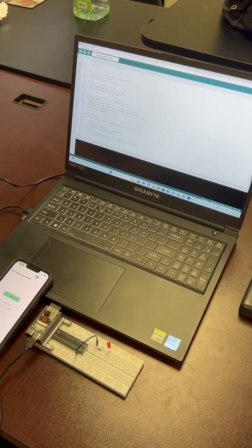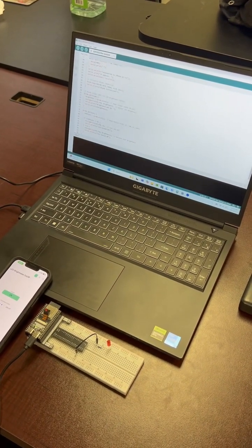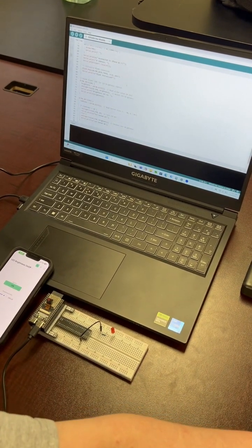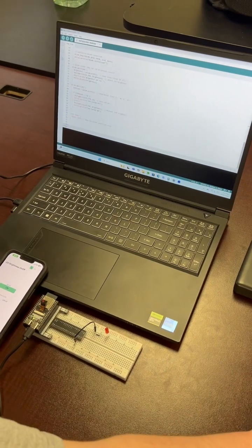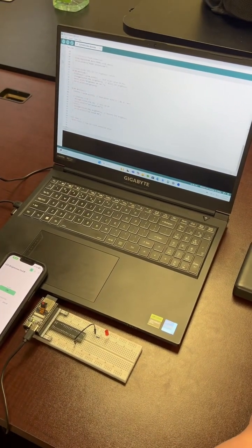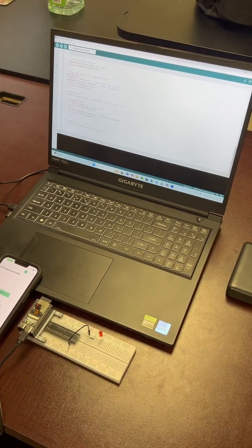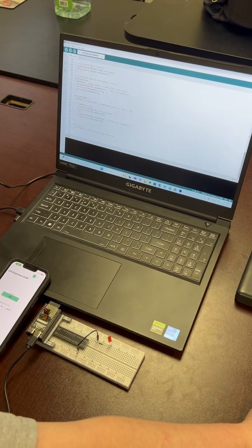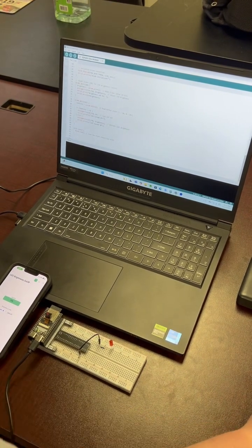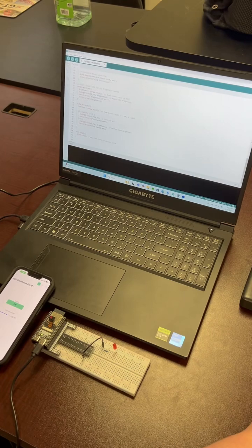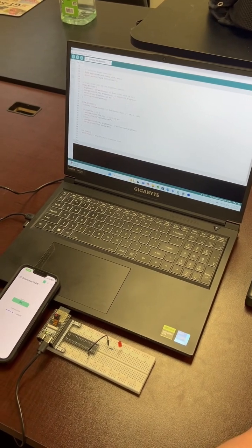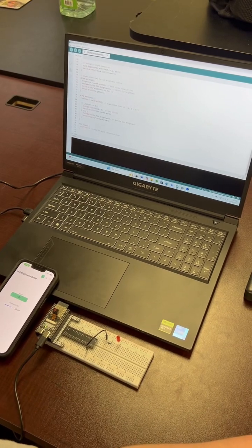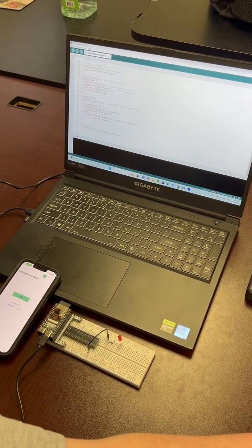And then here we actually connect to Blynk using the authentication token and then our Wi-Fi information, and then we're going to print that we're initialized. So our Blynk write commands is where we're going to actually interact on the app with our LED pin. So V0, that's going to be our slider for our brightness control. And then our brightness is going to be read from our slider on our app. And then whatever our slider value is, it's going to change our LED brightness to that. Then it's going to print what our brightness is.